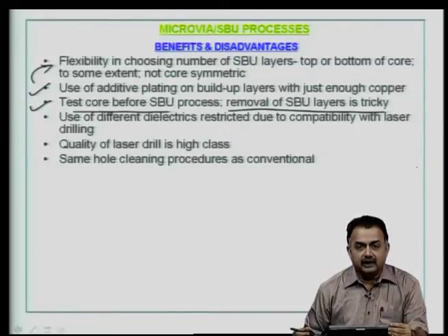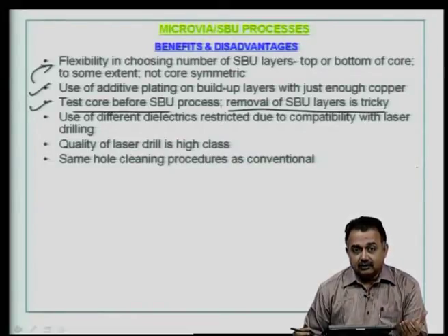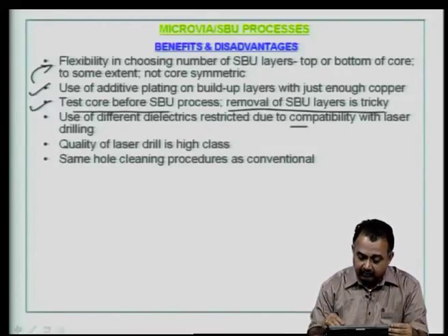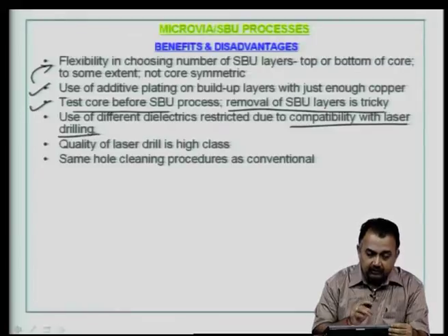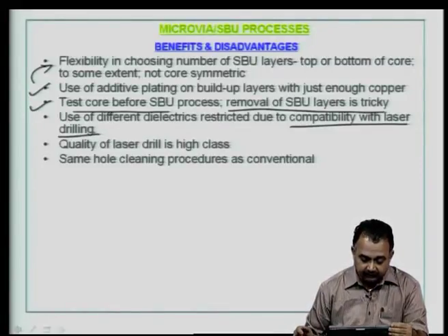Use of different dielectrics can be restricted. Ideally you want to use different dielectrics for different layers to improve the electrical performance, but it can be restricted due to compatibility with the laser drilling. So, ensure that problem is not there before you design that. Quality of laser drill is high class.